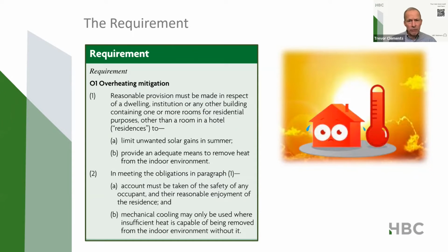You notice that phrase, rooms for residential purposes. I know the audience is made up of a lot of building control people who will know what that means, but for those of you who don't, that doesn't relate to houses or flats, although they are, of course, covered by the requirements. It's rooms used to live or sleep in, such as a hostel or a boarding house or a hall of residence or a residential home, maybe. That it doesn't include hospitals, just maybe a nursing home or something like that, or a retirement home.